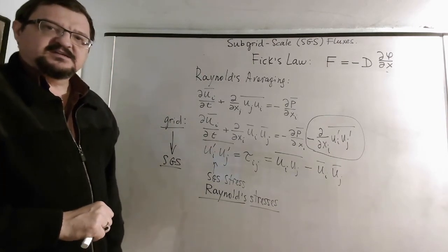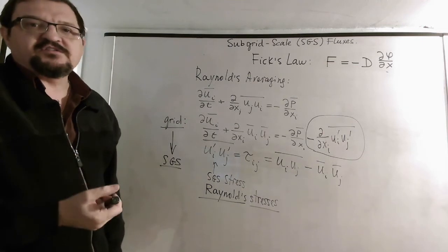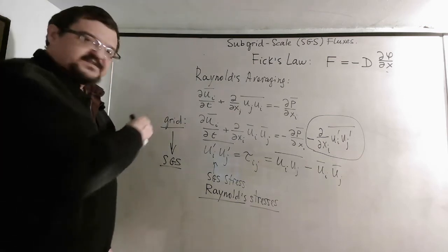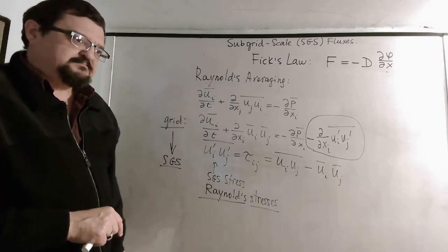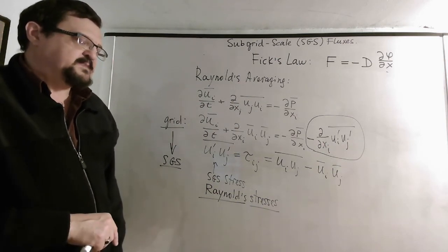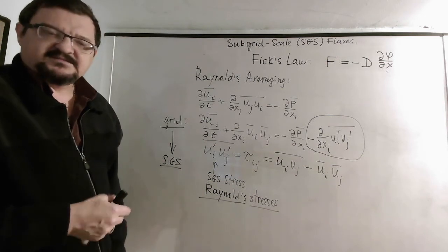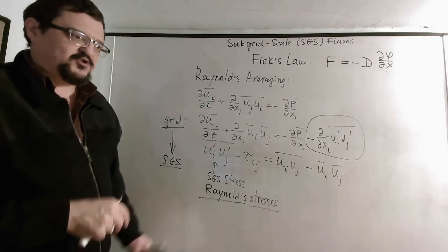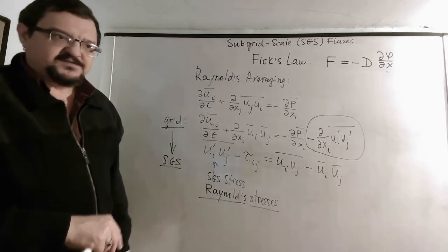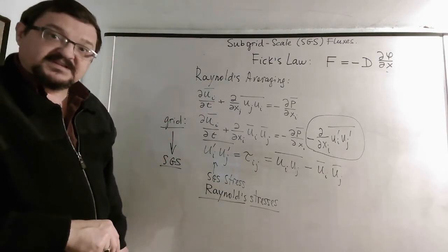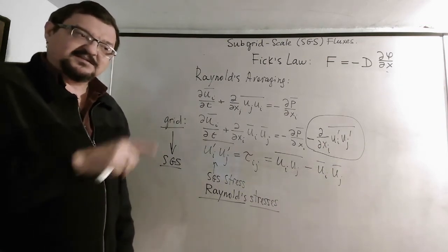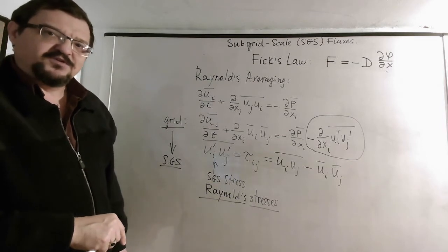Well, technically speaking, it's a very difficult problem, right? It's not necessarily true that subgrid scale fluxes entirely depend on grid scale information. For example, let's say you have lots of buildings on the surface that generate turbulence, and your grid spacing is much bigger than your buildings. Then your mean flow over those buildings and the turbulence around them will be determined by the distribution of those buildings in subgrid scale, not necessarily by the mean flow which is flowing above.